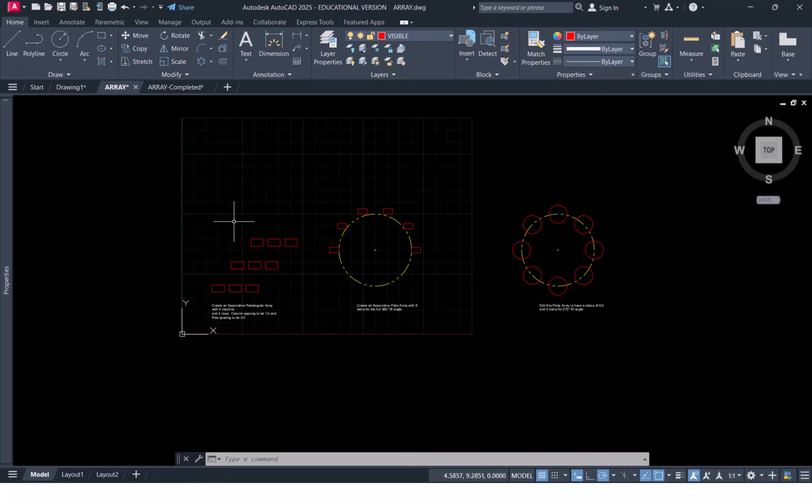So I'm giving you this file that you can practice in to see how these things work. You don't have to turn it in or anything like that. Just practice to get a feel for it, and you'll see how using an array can help you in a lot of your drawings, especially the polar. In mechanical drawing, you're going to see a lot where you've got a bolt pattern or a hole pattern around a circle, and it's easier than drawing individual things. So that's how it works.